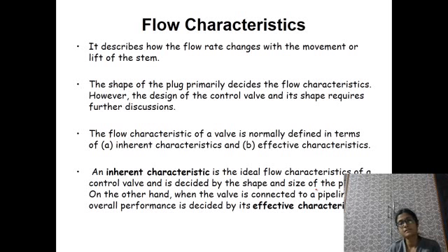Inherent characteristics means ideal characteristics, that is, the characteristics of the valve type itself. And effective characteristics means that when the valve is connected to the pipeline, its overall performance is decided by its effective characteristics. That is actually the performance of a valve used in a particular flow line.